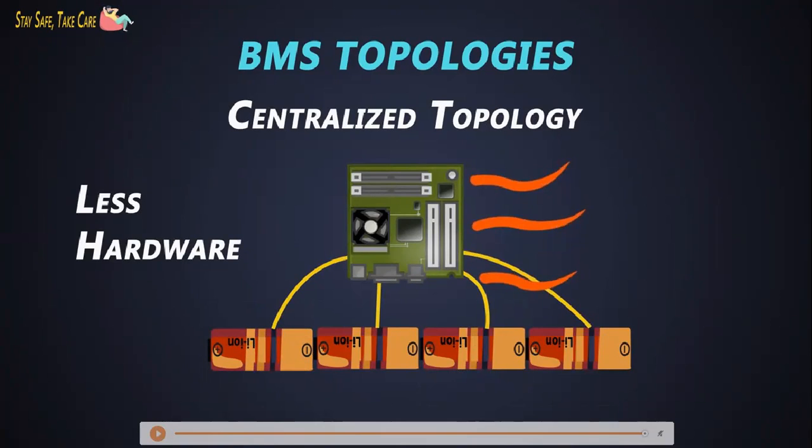Using this topology decreases the hardware, but excess heat could be generated because the controller is the only source for cell balancing in centralized topology.